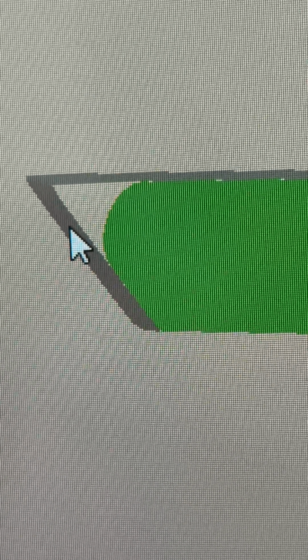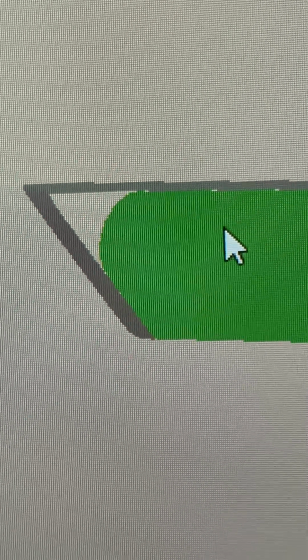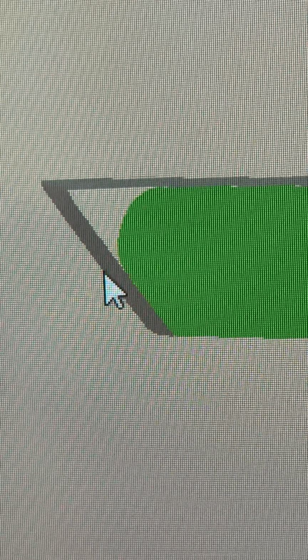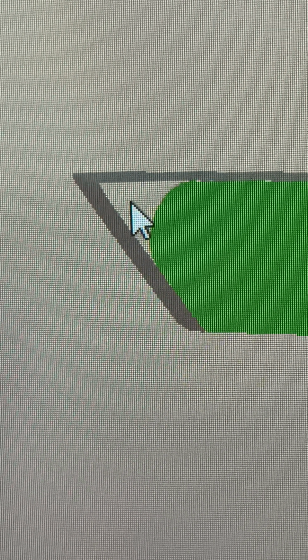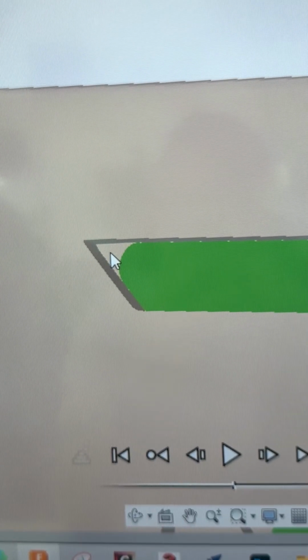And then there's even smaller end mills. But once you're getting into something like, if this is a stainless steel ball marker, using 1/32-inch end mills, you're going to break a lot of end mills to achieve corners that are still rounded, just rounded more or less, I should say. So that's the whole process behind milling and why someone might choose a mill versus a laser.